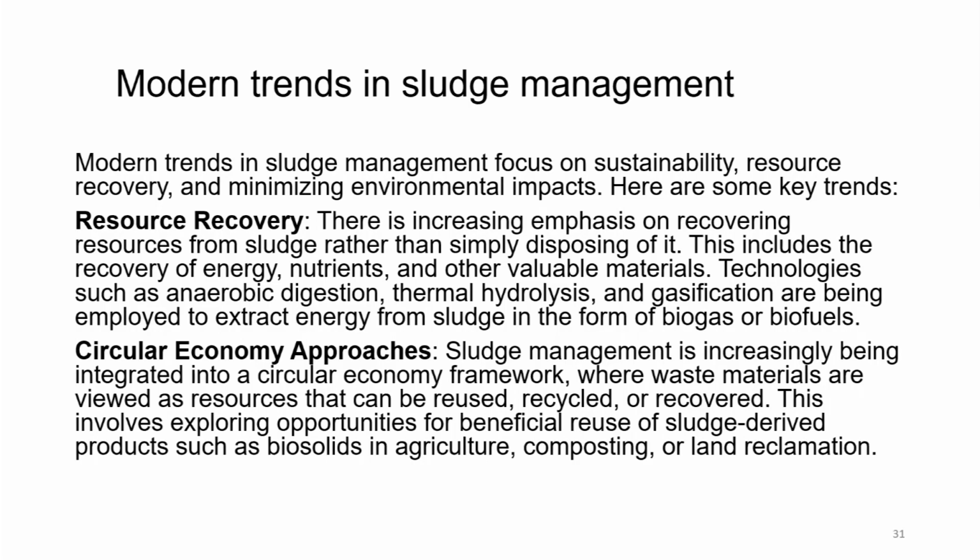Resource recovery. There is an increasing emphasis on recovering resources from sludge rather than simply disposing of it. This includes the recovery of energy, nutrients and other valuable materials. Technologies such as anaerobic digestion, thermal hydrolysis and gasification are being employed to extract energy from sludge in the form of biogas or biofuels.